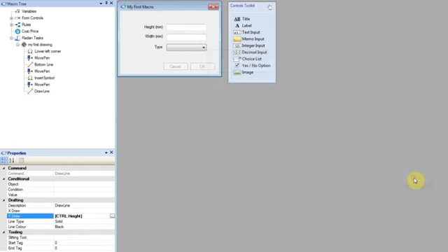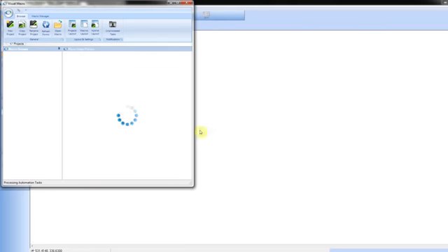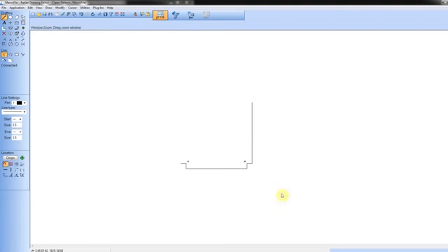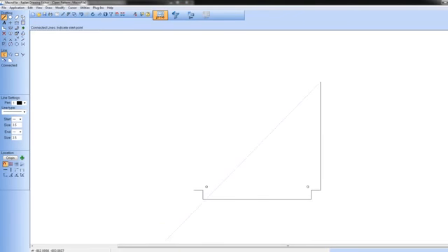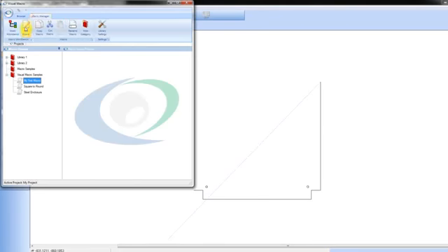Again, save and test the macro. Your drawing should look something like this. Go back to the macro in the workbench and select the automation node, right-click and add a Draw Line node. Now set the property to draw in the X direction by -width plus 100 like so.